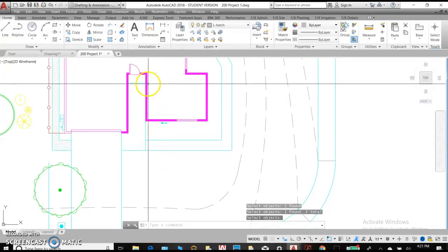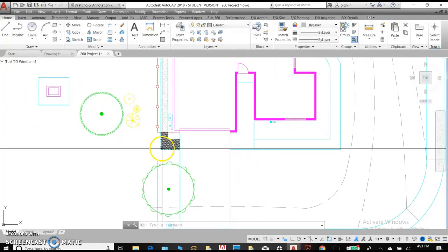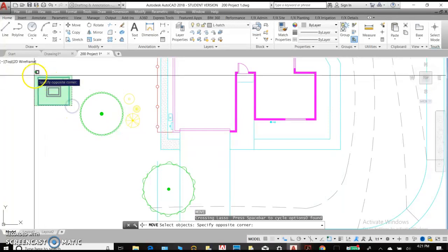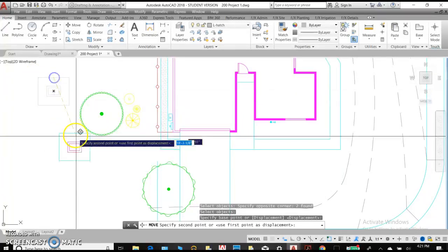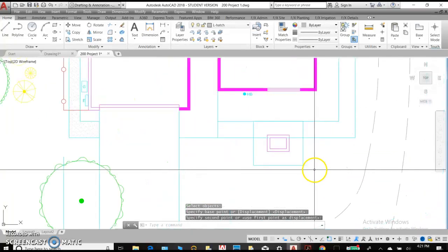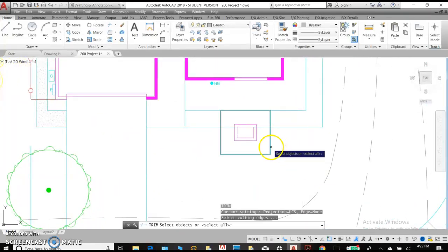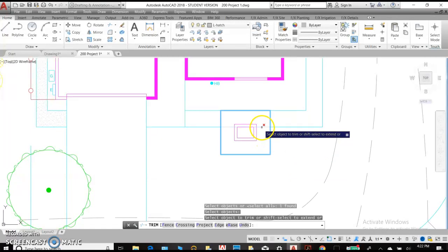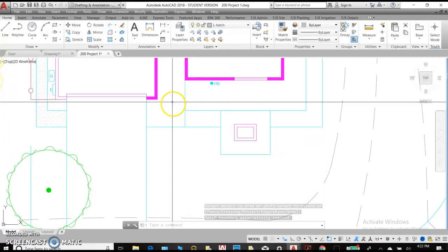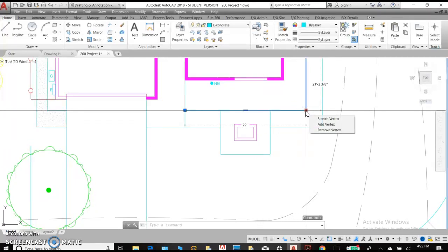So now this is one solid concrete area with a porch, and this walkway is existing, but we're going to go ahead and change it. So we're going to move by typing in M and selecting these objects, relocate those from the midpoint to the midpoint of the concrete walkway. From here, trim, hit enter, and trim away that piece of walkway. So now we have concrete walk all the way around here, and then it's going to end at this turn.